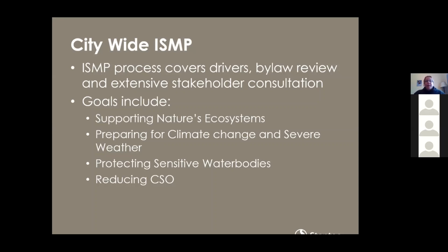Now, because they are a pipe system, technically, they're only concerned about water quality, but they're also about 25 years into a 75-year combined sewer separation program. So they are infiltrating water and removing volume from the system in order to offset predicted climate change increases that would affect the storm system.